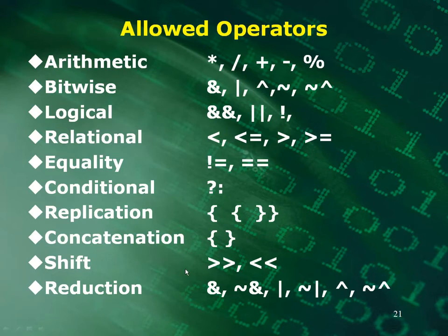Like in the example before the lecture, you're going to have to write some sort of test bench, and then you'll compile that code along with your real RTL code. In my case, the real RTL code was the one-wire transmit and the one-wire receive, and then I have a test bench that drives that. There wasn't very much in what I showed you as far as driving it. It just ran a little ways and stopped, so I could look at the signals. But you could have it check. In your test bench, after it goes a certain amount of time, you might want to test the read values, make sure you're getting back the right read values, and if not, you print out some statement.